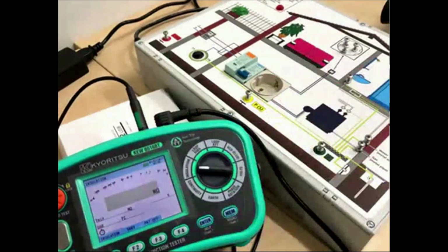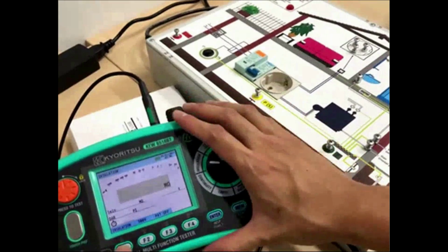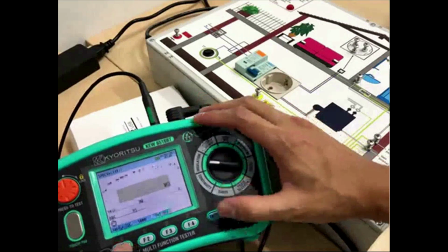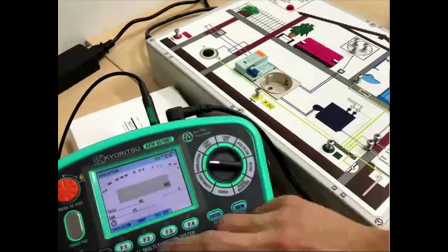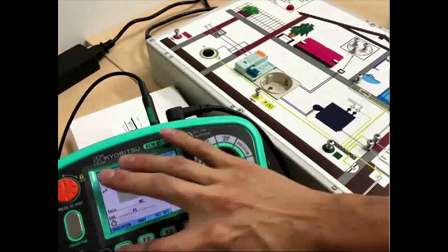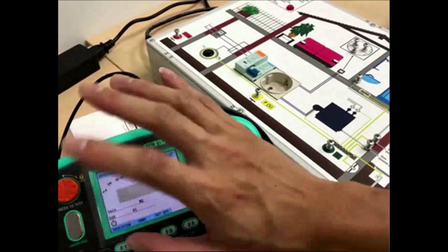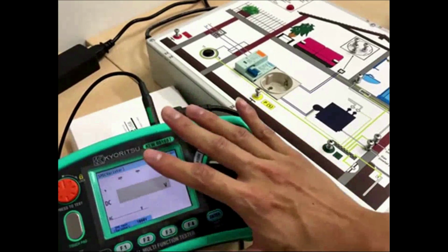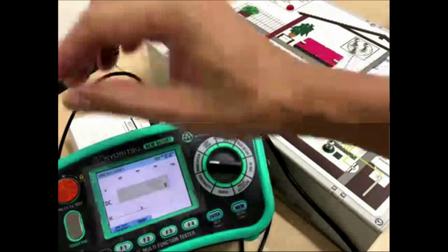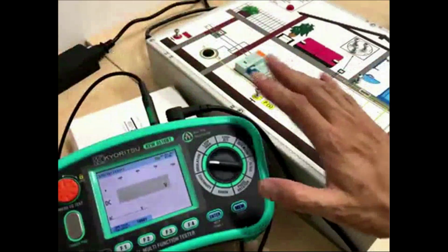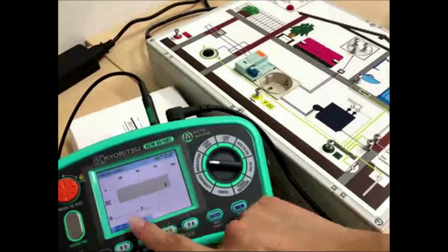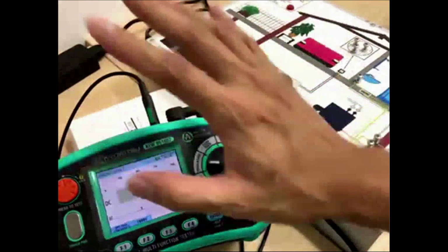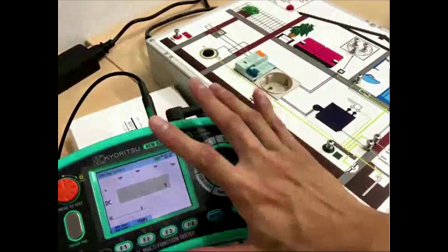Insulation. Inside the insulation, there is an SPD test. For example, just now I taught you how to play around with this function key. Just press, it won't spoil. Just press. See, SPD test. So SPD test, I won't show you. But when you connect, like the diagram I showed you just now, then you press the start key, it will count from 0 volt, 0 until 700 volt. It breaks down. So meaning to say the SPD breakdown voltage is 700 volt, like that only.